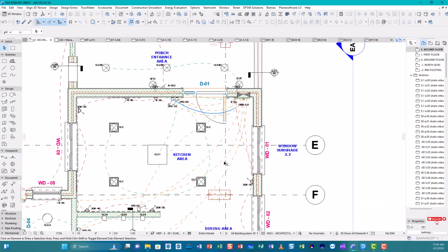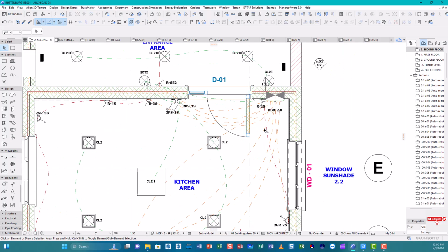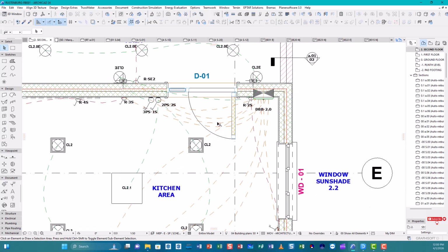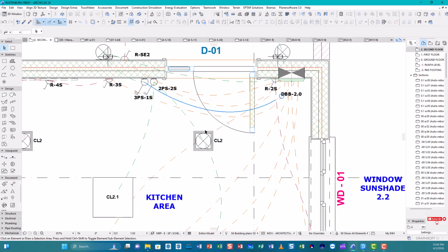Because I know that after doing this, I will take the data from ArchiCAD straight to AutoCAD Electrical. Then I'll build up the distribution box with all the fuses, the MCBs (miniature circuit breakers) that are needed, and the leakage breaker needed for the full project. The orange ones, as I say, are power cables. And what I will do in the future about these cables is to annotate them. That is a must-do for me.